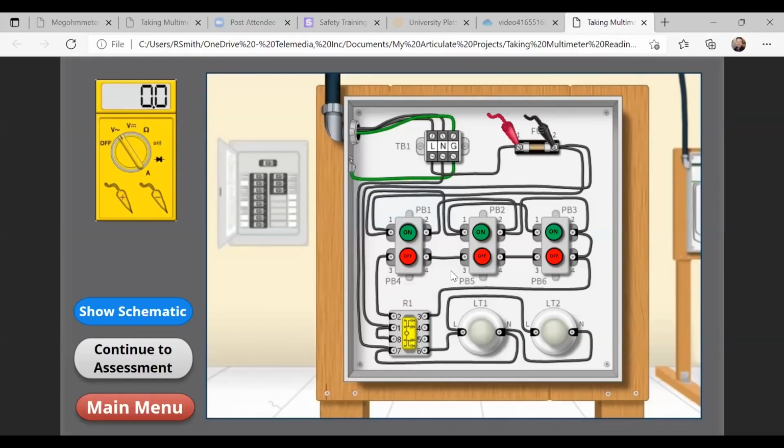Well, that really starts speaking to the nature of what voltage is and what we're actually measuring when we get a voltage reading. Voltage is not telling us, and this is kind of back to the question Greg posed at the beginning, does 0 voltage mean our circuit is de-energized? And in this case, the answer is no, that is not necessarily what it means. If we're getting a 0 voltage, that's not necessarily telling us that the circuit is de-energized. What it's actually telling us is that the circuit is experiencing no potential difference from this point to this point. So from point 1 to point 2 or point A to point B.